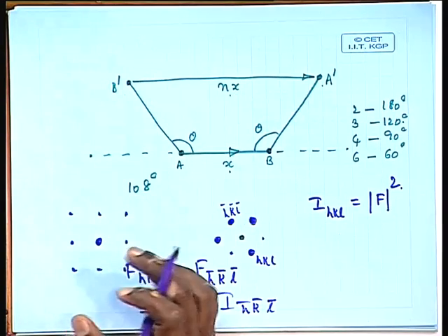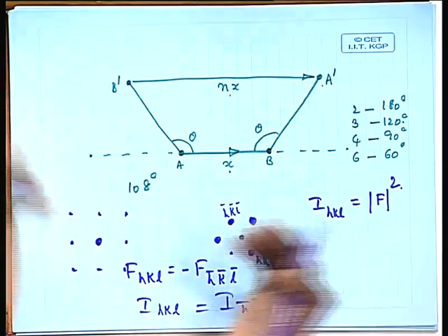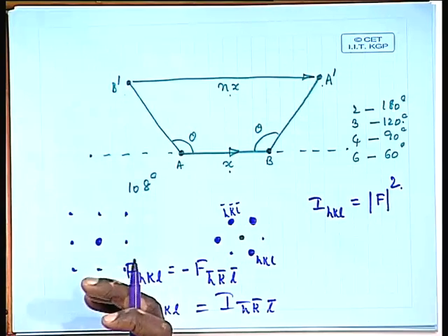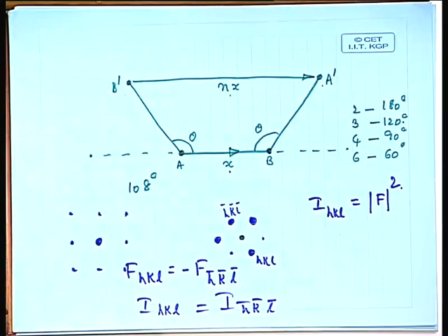From the crystallography we know what the angles are. What is the angle between the 100 plane and the 111 plane? This angle is known, 57.3 or so. Once we know these angles from the crystallography, I can tilt the sample by that particular angle and get this 4-fold symmetry. If I don't get that 4-fold symmetry, then it is clear it is not cubic, it has to be one of the other 2. Isn't it? That's how one can find out.